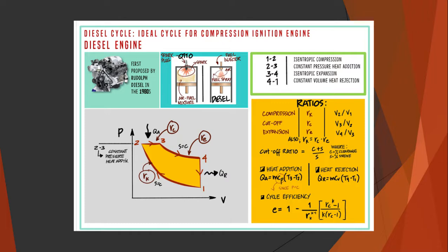Then there is also no blow-by loss. The leakage of compressed gases causes the blow-by loss through the piston rings and other crevices. And there are also no frictional losses here. The next topic is the thermal efficiency for the diesel cycle.